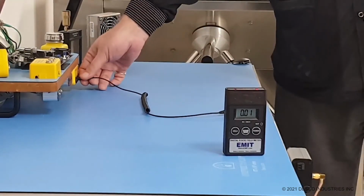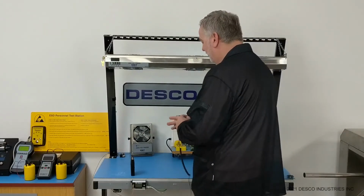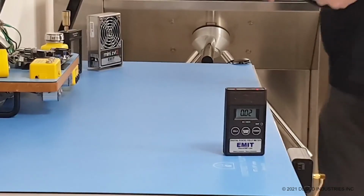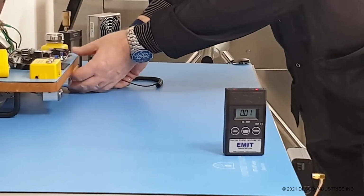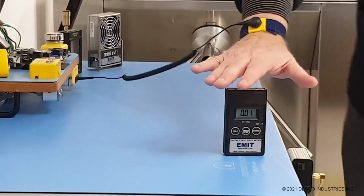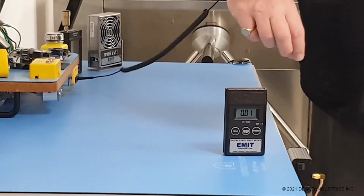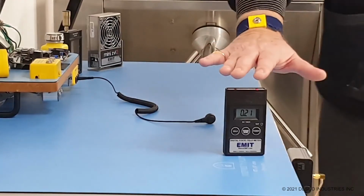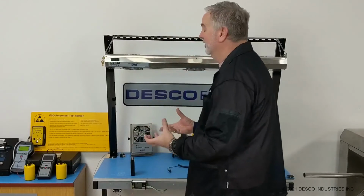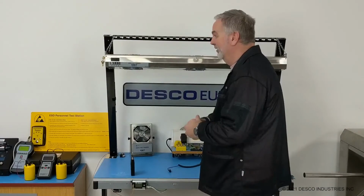If I then take a wrist strap set that I've got here, place that on my wrist so it's making snug skin contact, plug it into a grounding point, and do exactly the same as I was doing before and move around, you'll see that there is no voltage being generated. And just to show you very quickly, if I disconnect that and then again do the same movements, you'll see that the voltage is back. So that shows the effectiveness of wearing a wrist strap, that it takes the charge that's being generated and takes it away to ground safely.